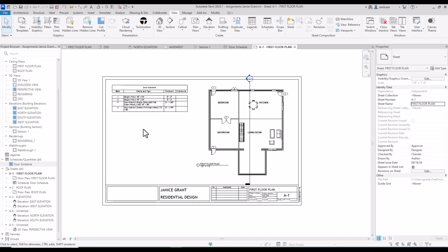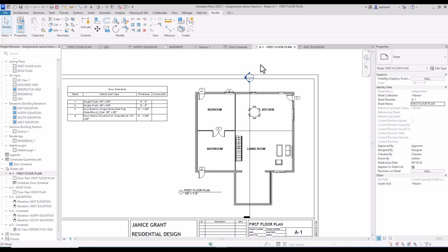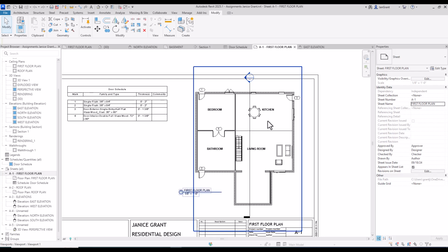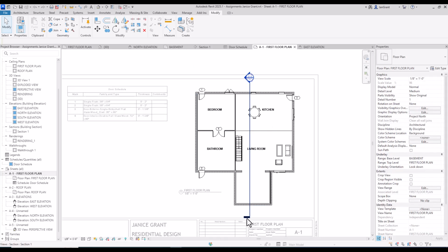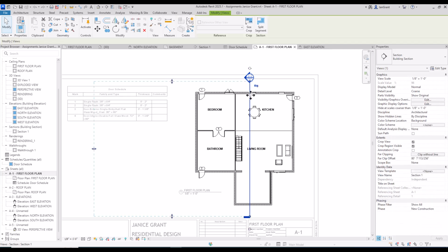So the last thing that I'd like to talk to you about is to be able to change some of the line weight. And so since you're here and you're getting all this ready for your portfolio, that last project, we want to clean this up a little. We can double click here to go inside this view, click on your section and just drag this head down just a little bit so it's on the sheet.